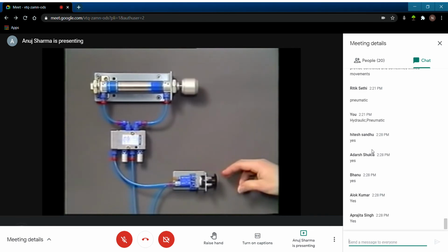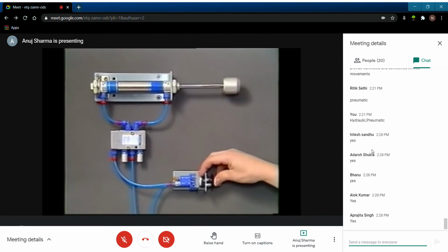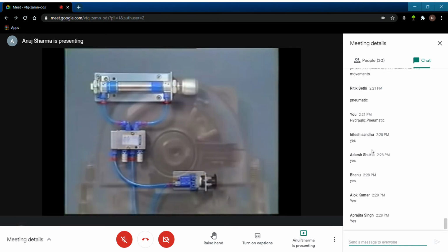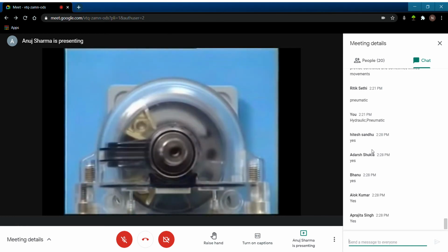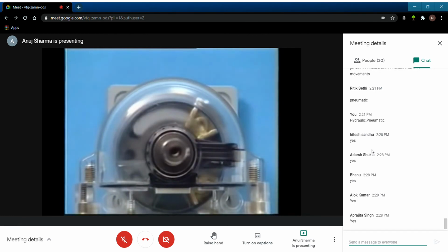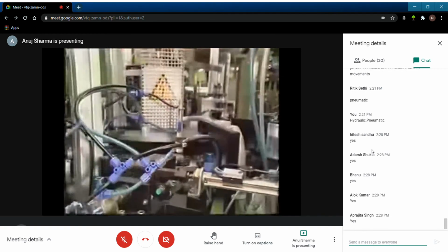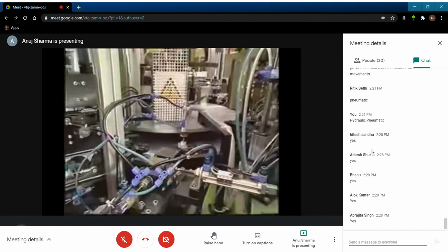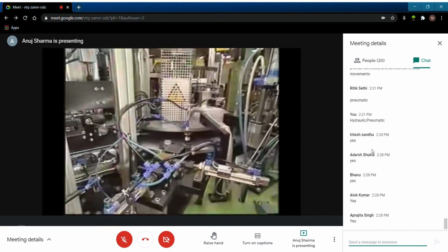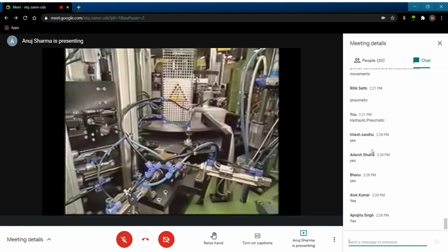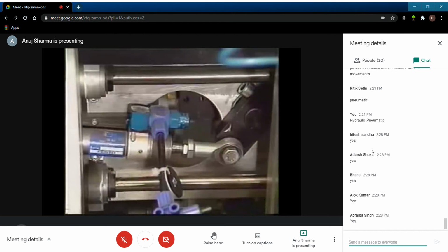Pressing the button sends air to the cylinder. The control valve in the center of this circuit determines which side of the cylinder receives the air. The push-button valve at the bottom of the circuit sends signals to the control valve. Therefore, compressed air acts as both a working and control medium. Pneumatics, or using compressed air to transmit energy and control functions in systems, has several advantages. Let's examine examples of each.